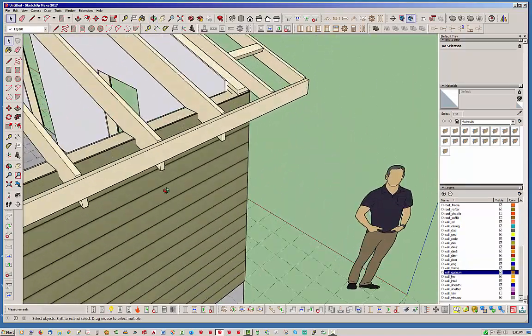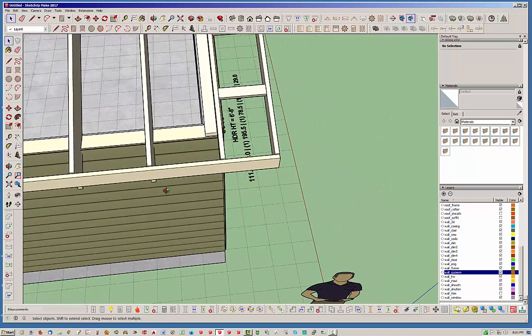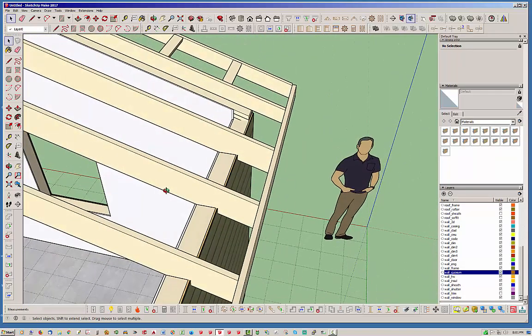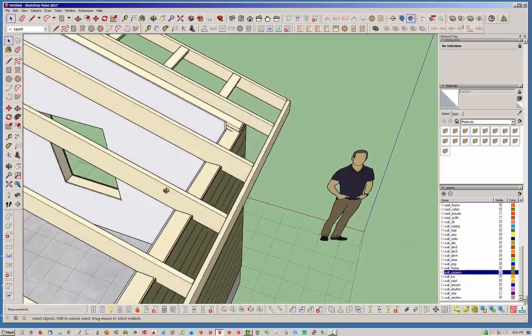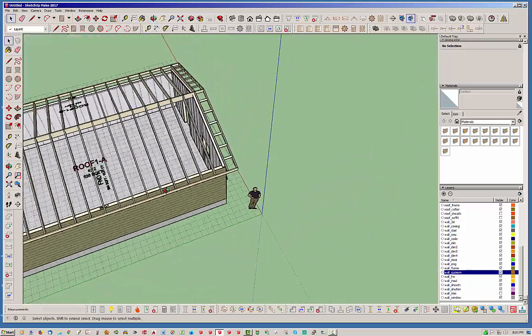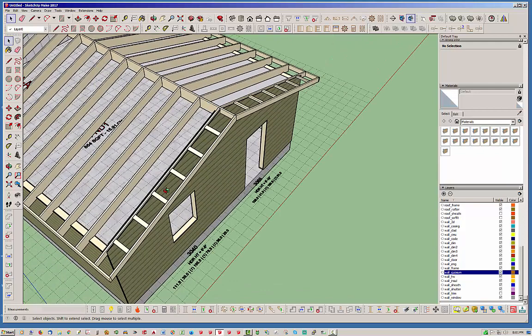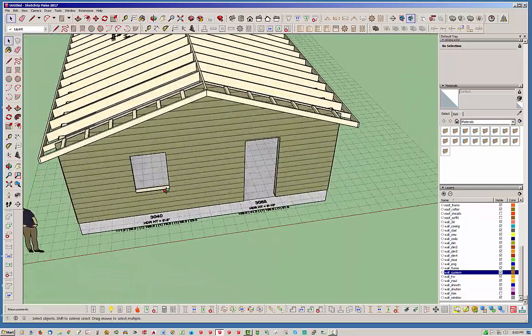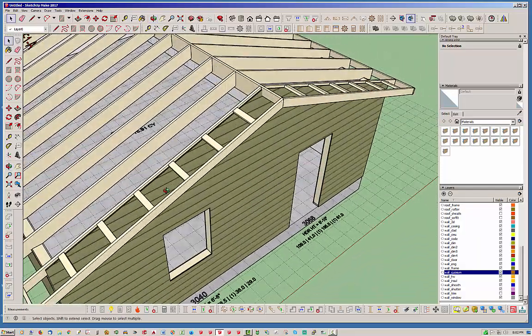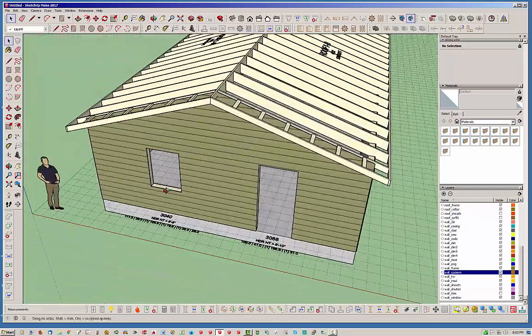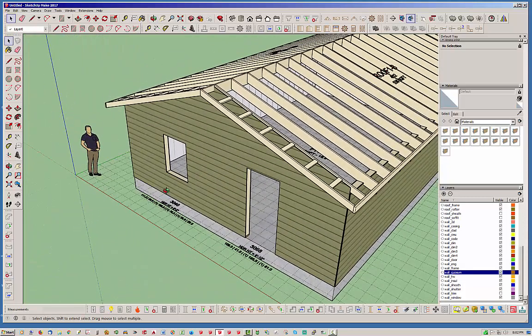And maybe that doesn't extend all of there, maybe it extends over to this top of this, and if it doesn't, we can trim it some more. But I think you get the idea. The key takeaway here is that this trim tool that's included with the Truss plugin is a very valuable little resource for manually editing these members. You can see that it's pretty quick and easy. It's not as bad as one might think.